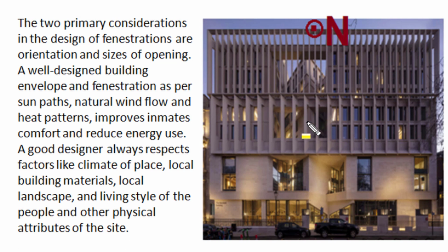A good building design always respect factor like climate of place, local building material, local nearby landscape and living style and functional requirement of people who use this building and other physical attribute of the site. Here this is a north facing part of building and maximum positions and size of fenestration is provided on this north facet of the building, and this is as per the design requirement for energy efficient green buildings.